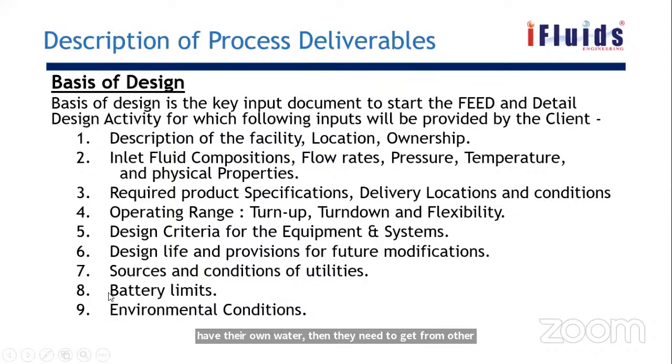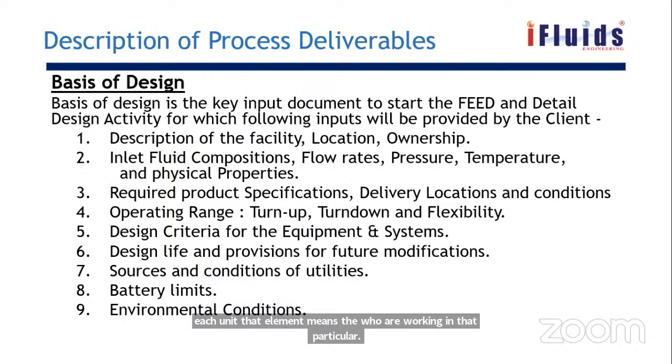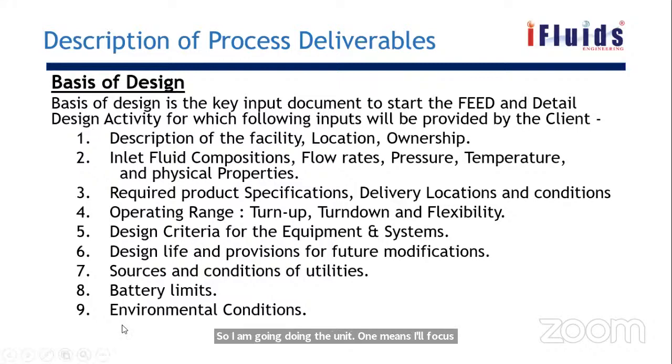And the battery limits will be defined, since a refinery has multiple units. So each unit will be provided with battery limits. Battery limit means those who are working on that particular unit will not go beyond this, even for the design. So if I am doing unit 1, I will focus only on unit 1. And the environmental conditions relevant to that local area, and then the government norms, all those things will be given in the basis of design.